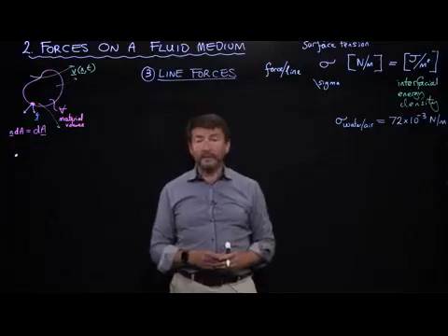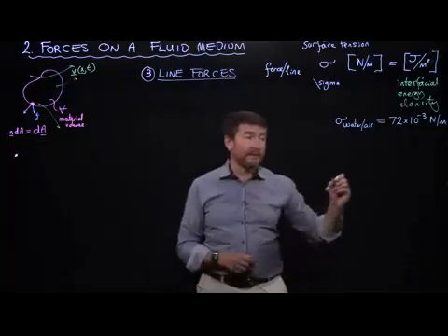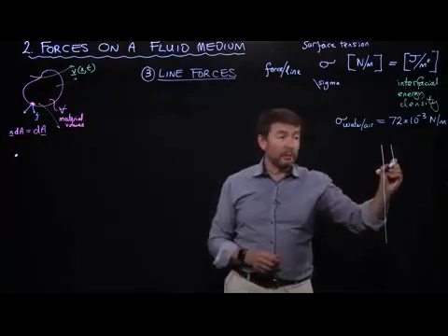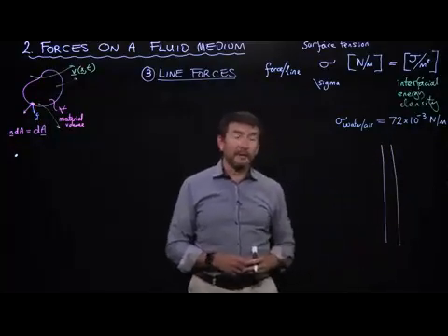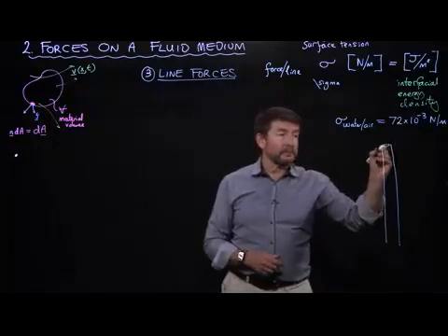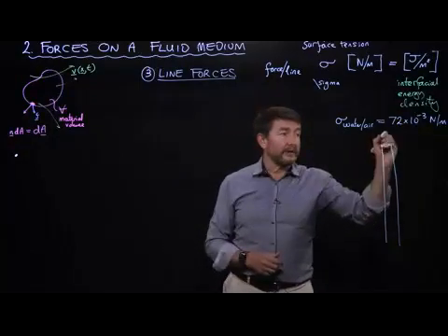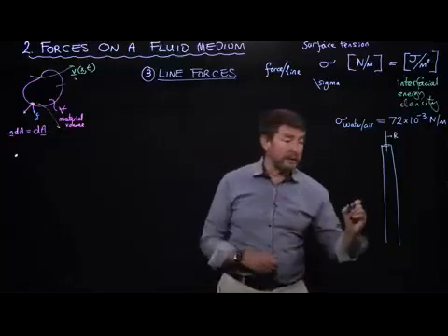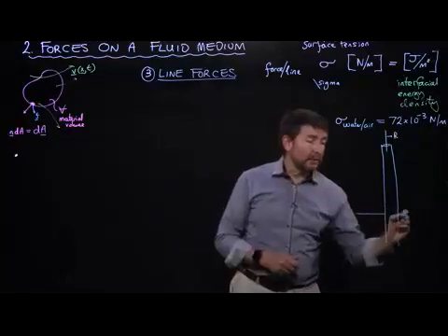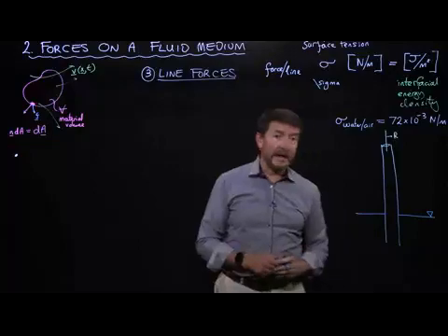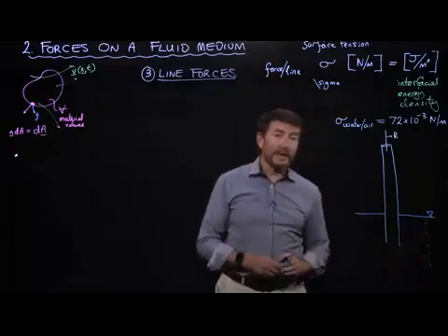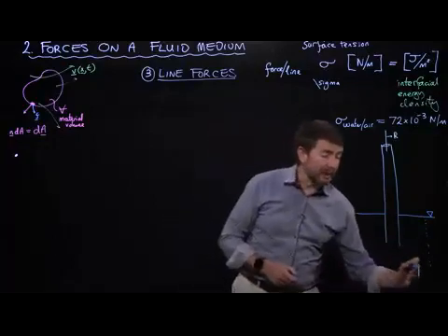And so we're going to think about an example to explore this and to see what happens. A good example to think about is what happens if you're making very, very small channels. So if I'm making very, very small pipes, let's say that the radius of this pipe is R, and I dip my pipe into water, and it's open at the end, and water is sitting here at equilibrium, and we know that the pressure will increase in the water due to hydrostatics.